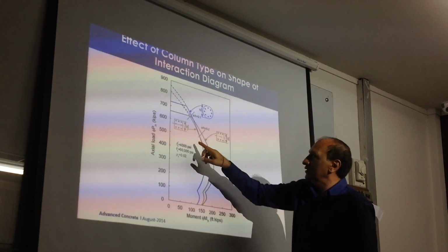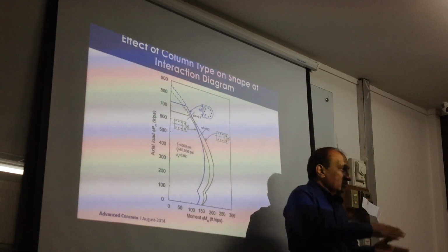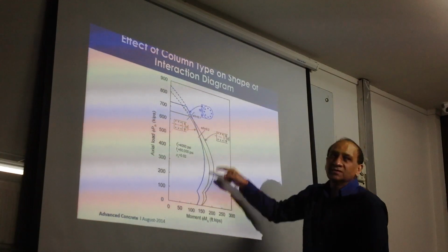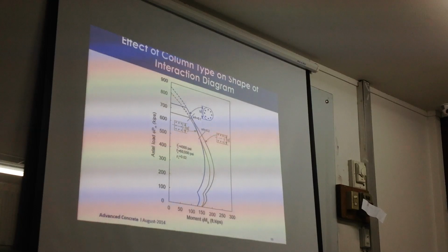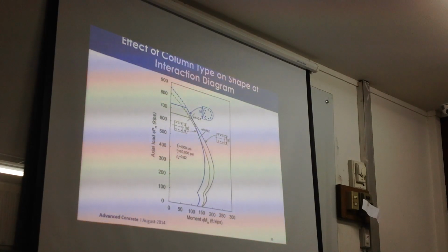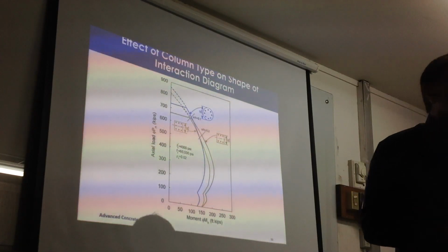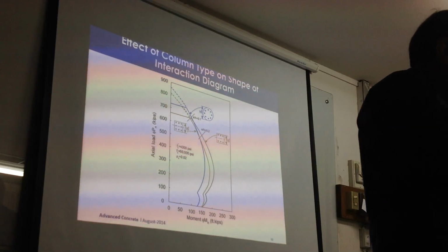And this one, you can see from here, the most efficient section will be this one, because all the reinforcement is close to tension and compression, providing you maximum moment capacity. Right? So if you put all of this reinforcement here, you get nothing. Right? So rebar layout is very important for efficient design. And you can optimize the reinforcement layout if you know the moment direction. But the problem is we do not know the moment direction because there are 4,000, 5,000 moment directions. Right? So the circle wins because it will work best in all directions.